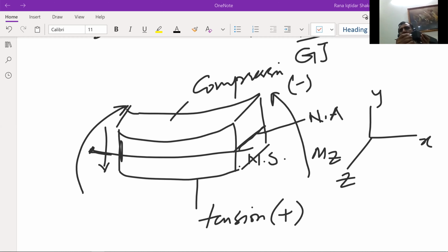This is what we know now, that from this expression, from this picture, at the neutral surface the normal strain will be zero, and resultingly the normal stress will be zero. But above that and below that, it will be varying, and that will depend, like the torsion we did, on the distance from the center.